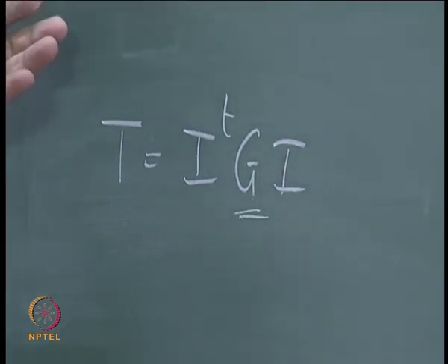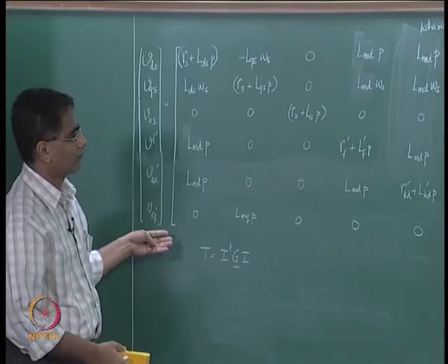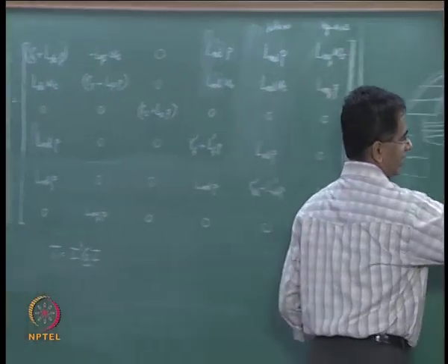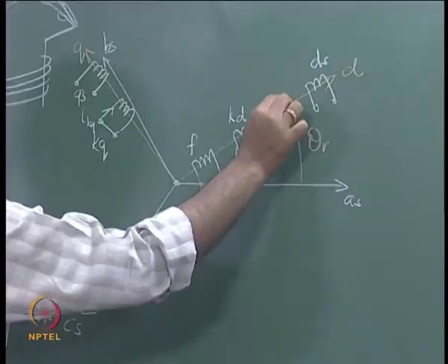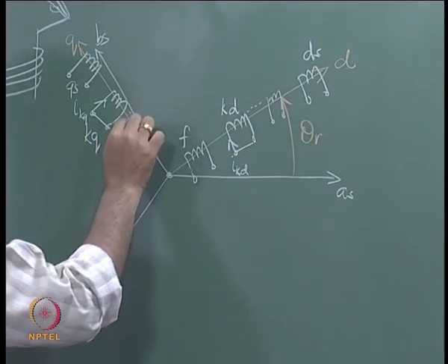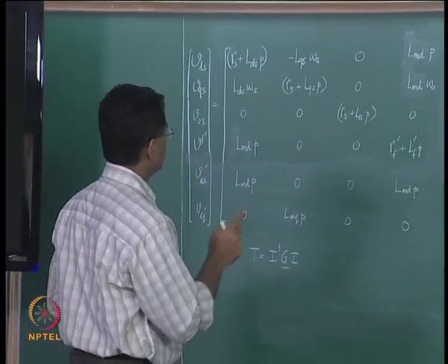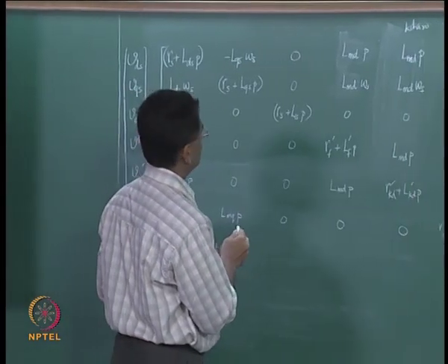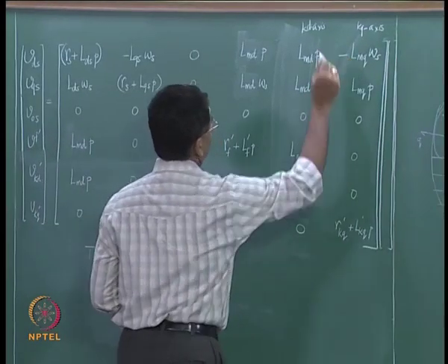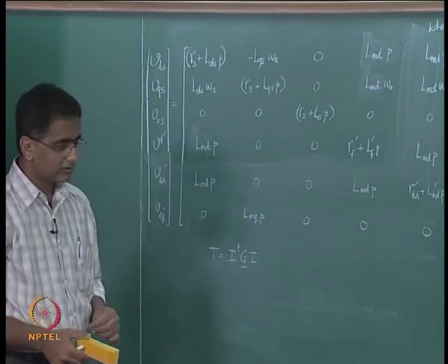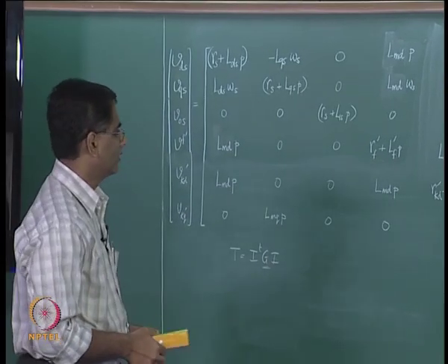So you can see that if you want to augment the description by having more coils to represent the damper windings, some more coils if you want, those can be added very easily by understanding how this representation is. There is one more aspect that I think I have missed, the speed EMF term here is negative. So that is then the synchronous machine equation.